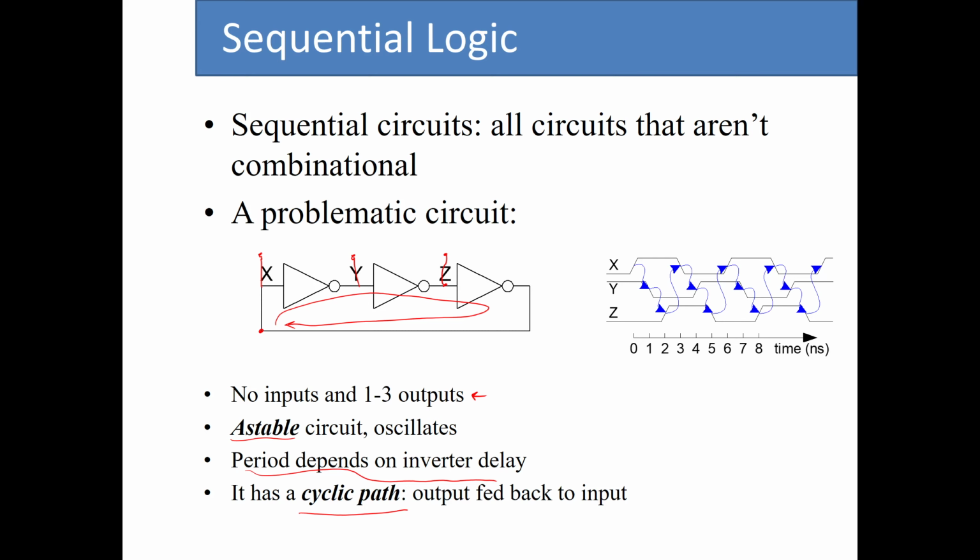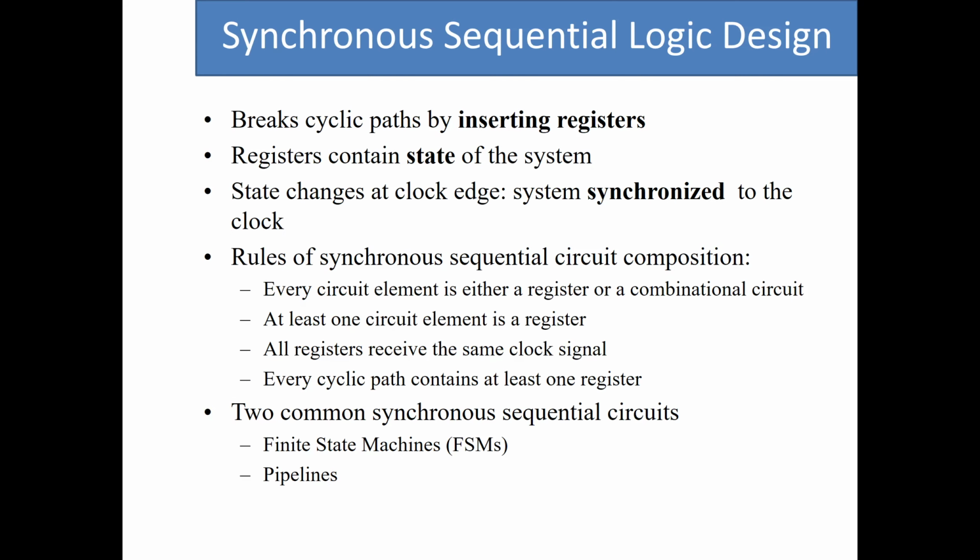So now that we have this, we can combine all this knowledge from before, and come up with a set of rules that govern synchronous sequential logic design. The first rule is that we have to break all the cyclic paths in the circuit by inserting registers or flip-flops.